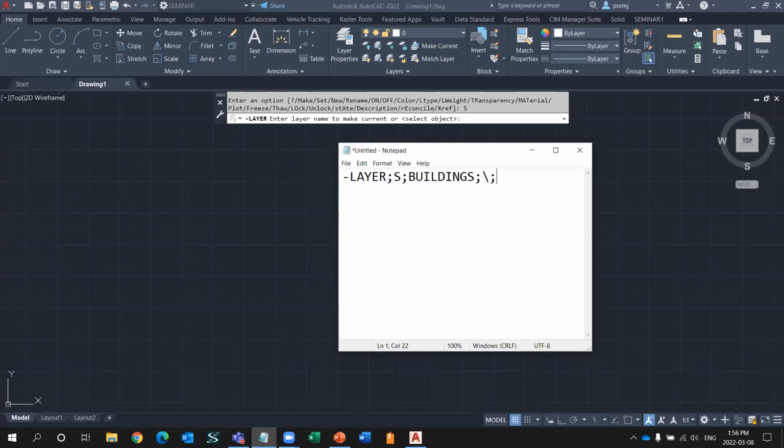Now, once that command is done, I want it to trigger maybe the AutoCAD insert command to insert the block. Similar procedure. It may ask you for the block name, then the insertion point, which is a pause sign. After that, upon inserting, then scale and rotation and things like that.